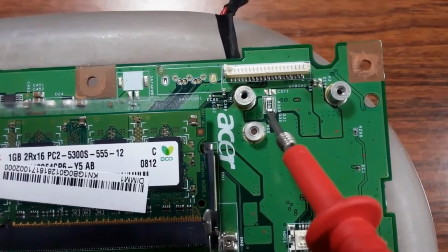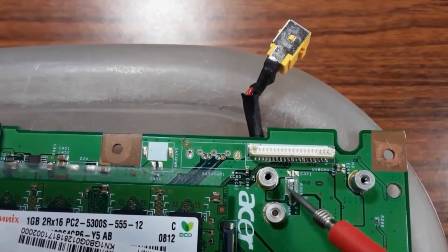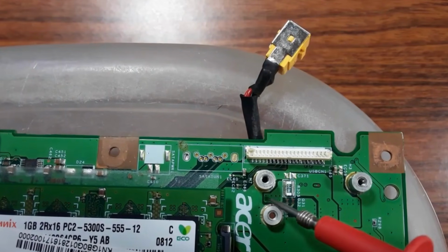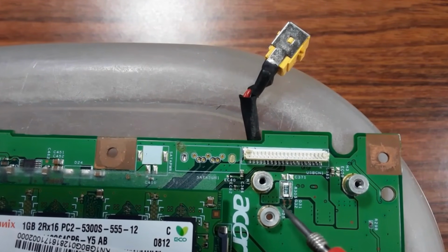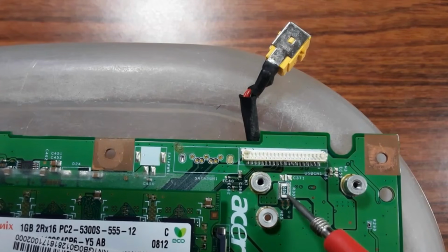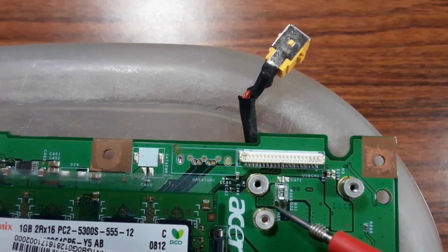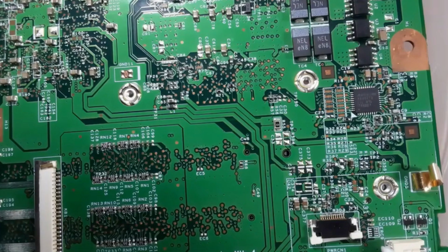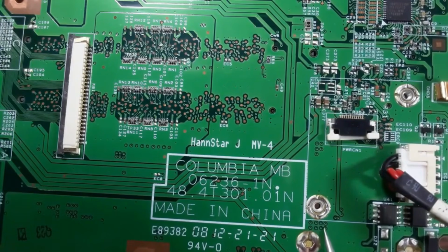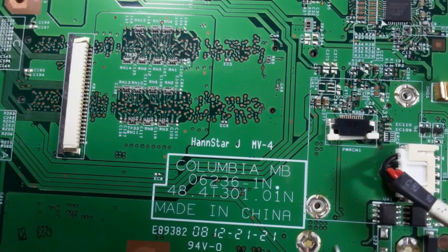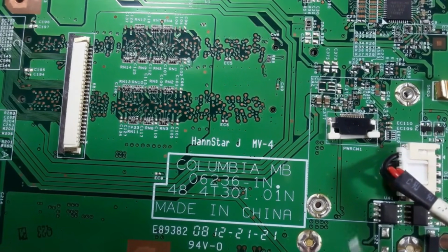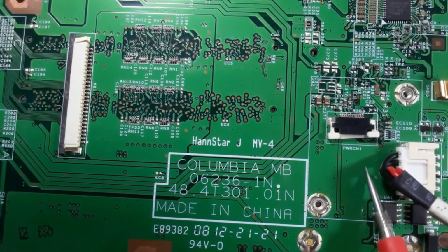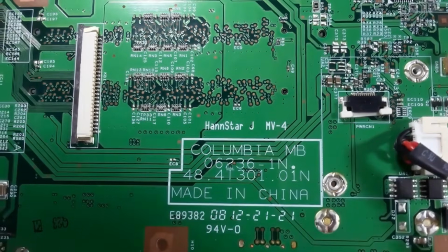And then, as you can see here, we have other dots. We have 1, 2, 3, 4, 5, 6, 7, 8. We have here 8 dots, means this is a resistor. A current sense resistor is connected to 6 components in the other side. As you can see here, we have 6 points. These points are not connected to this green color. No, as you see, we have here a circle. Means there is no connection between this point and this, because this is the ground. As you can see, this is ground.